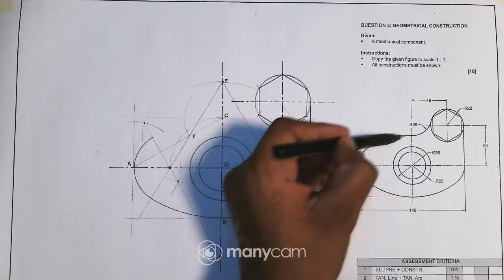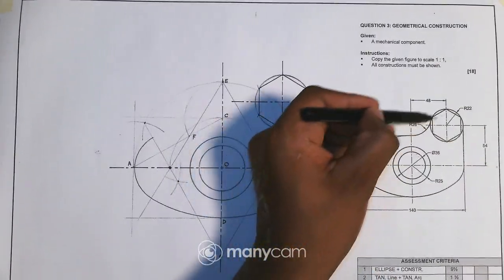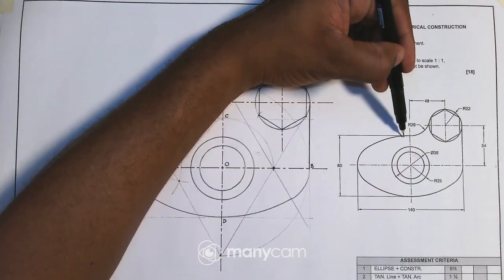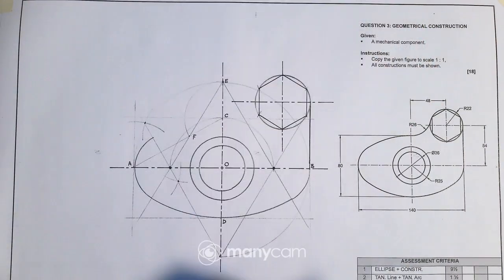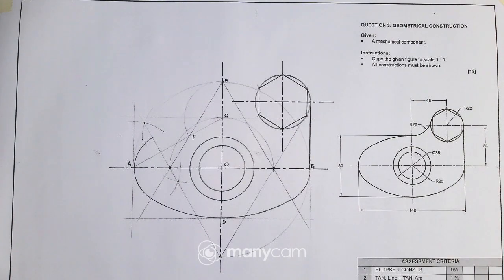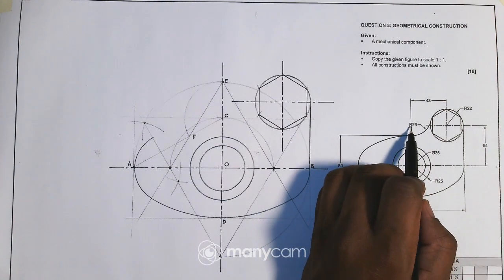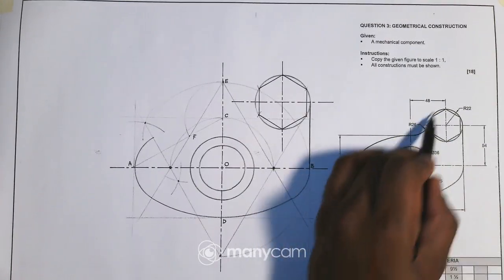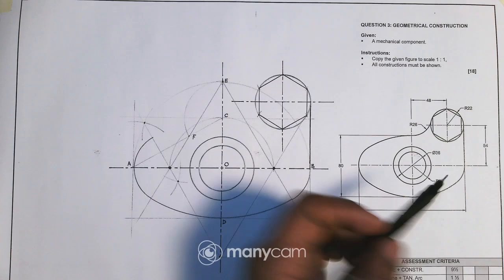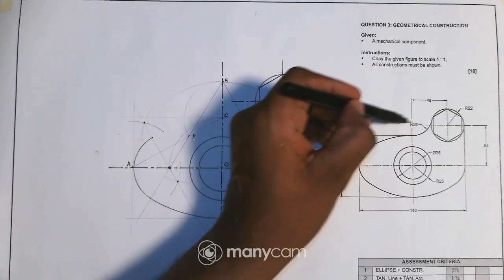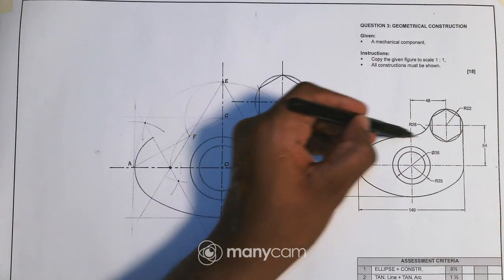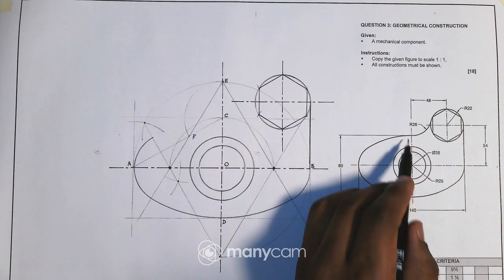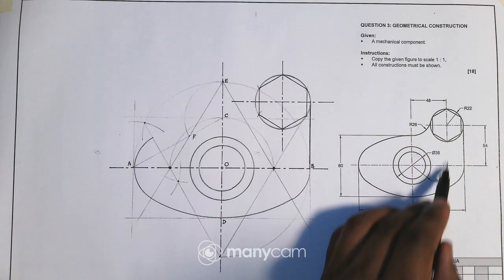If we have an excluding arc, we will add the radius for that tangential arc and the radius of that particular circle. So in this case, I'll have to add the radius for the tangential arc and the radius of this circle first. And then after that, I'll add this radius for the arc and the radius of the invisible circle.